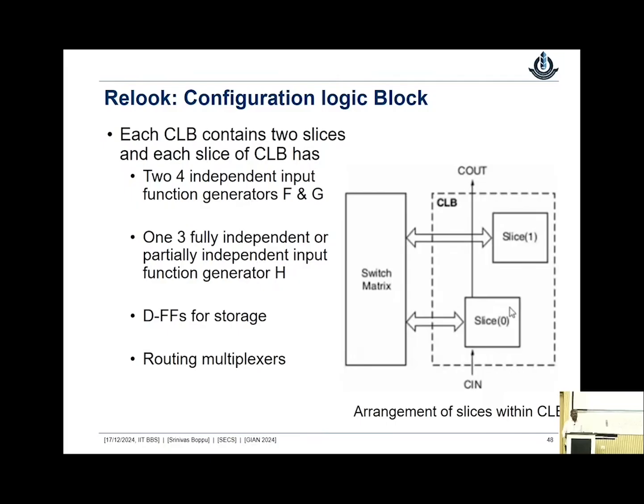Okay. So earlier, when I was talking about the CLB, I was saying that we have a LUT and this carry chain logic, right? Now I'm just changing the definition: the CLB contains what are known as slices, and the slice contains the k-input LUT and the carry chain logic. We can have multiple such slices, and here we are showing one configuration where the CLB contains 2 slices. So the k-input LUT and the carry chain logic, which I showed up front with the flip flop, are part of your slice.